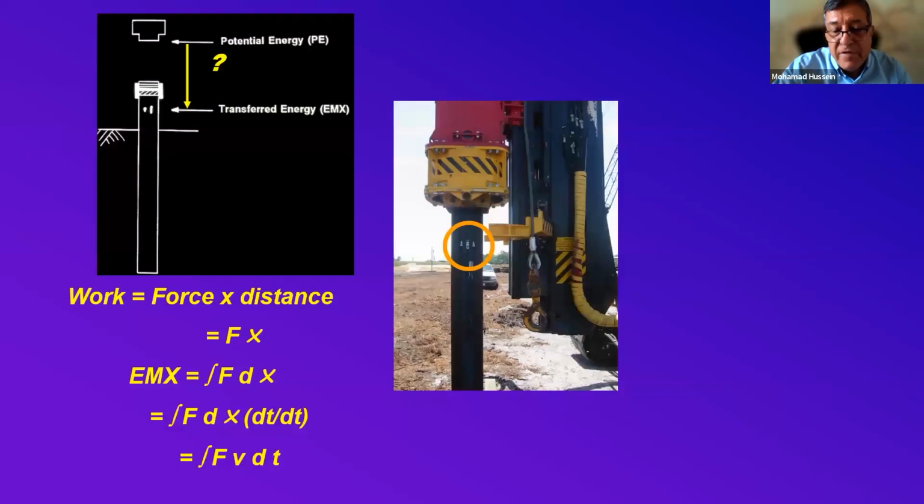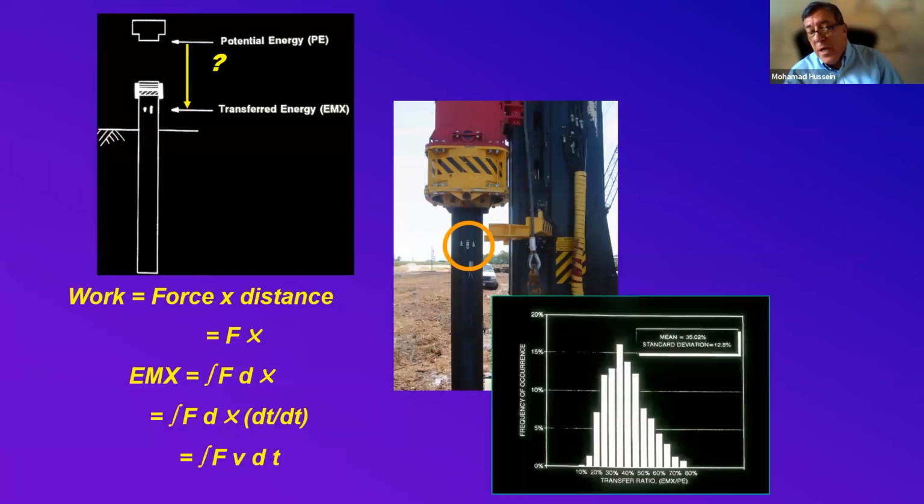Of course, the performance of the hammer is important because if we're going to relate the blow count to the load-bearing capacity, we have to have a good handle on the performance level of the hammer system. It can vary by a wide range. That's why it's important to measure it on each and every job site and use project-specific information.